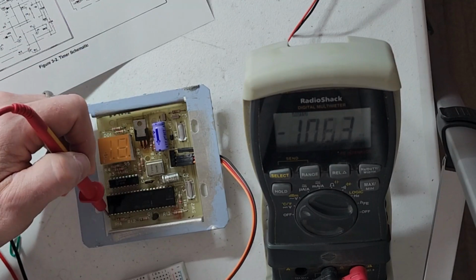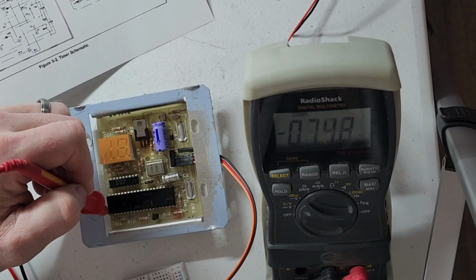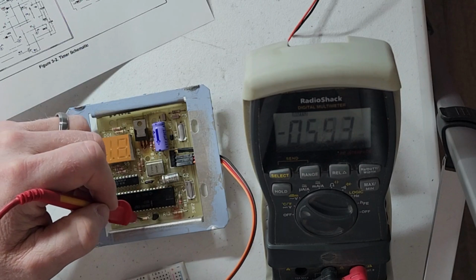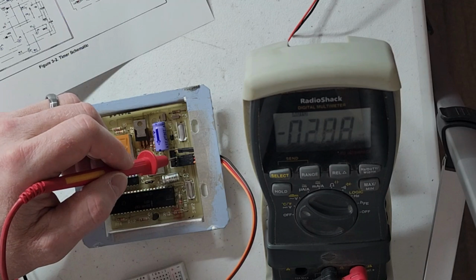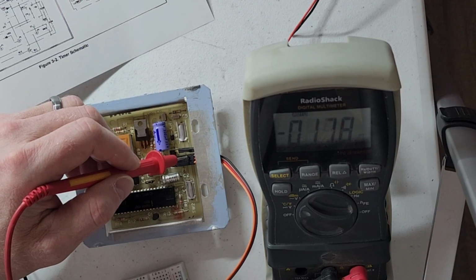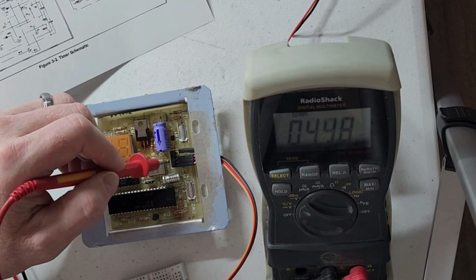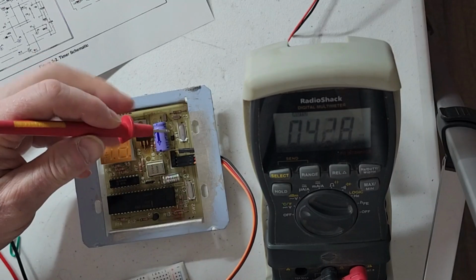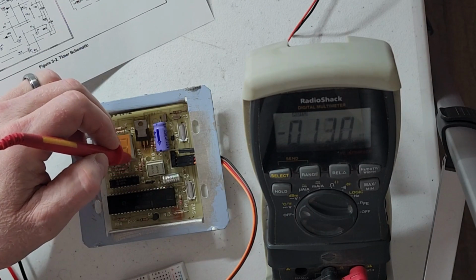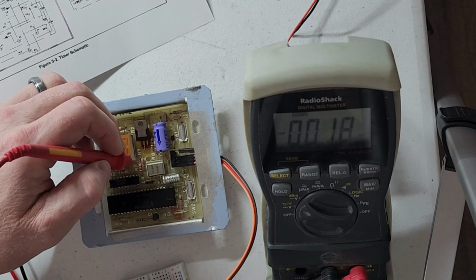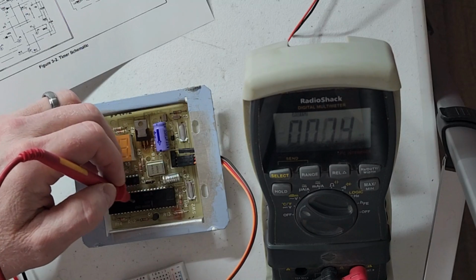I could keep this the same and just take this chip out, tie my Arduino output to this pin for the motor to turn on. This is just an input, a very simple input. That's just a dry contact to ground. So I could pretty much do the same thing with the Arduino. I could figure out where this is going. I'll bet you there's a resistor here tied to 5 volts and ground. That this, figure out where that's going, tie that into, actually it goes to,